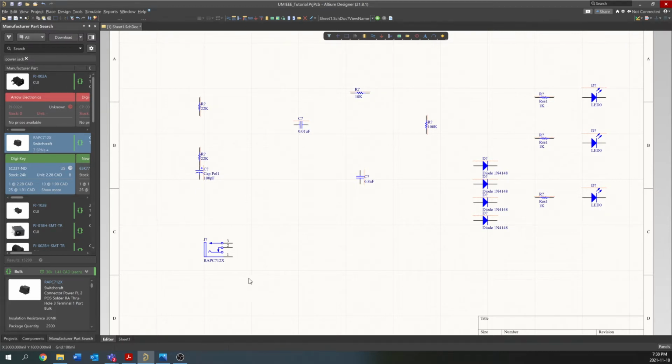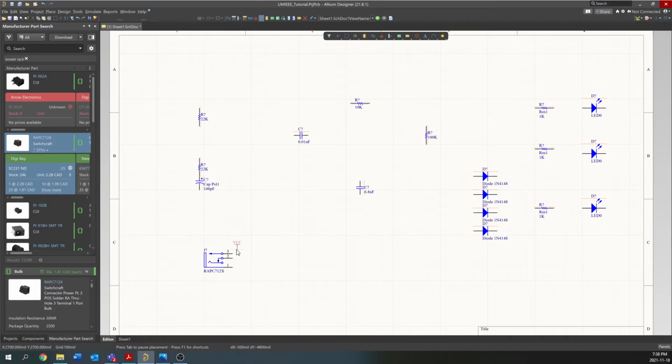Before we go any further, I'm just going to set that up as a power port here. Pin 3 here is the center pin of the power jack, so we're going to give this a VCC net. Up in the top here is my VCC power port pin, and we're going to click that. It generates a VCC, and I can keep adding it to various ports. Maybe I want a VCC up here eventually. Add another one there.